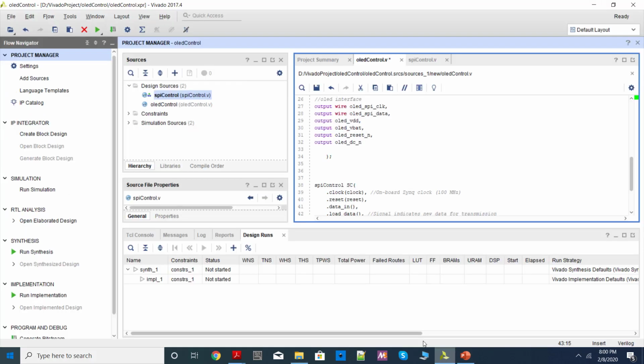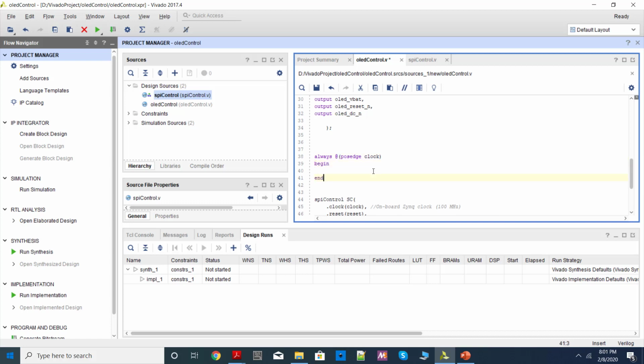Again, I'm not declaring any signal at this point of time. We will add the signal as we go along, as required. Okay, so I'm just declaring always @(posedge clock) begin end, if reset begin end. So every statement when you reset, it should go to a known state. So I'm going to use a register called state to store my current state, and I'm saying when I power up, I'll be in the idle state.